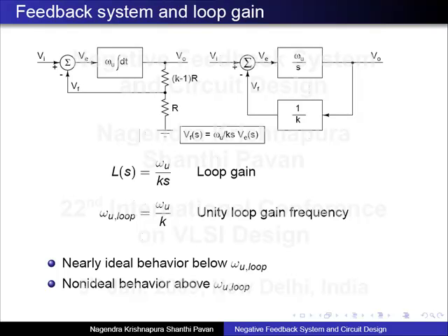What do you mean by non-partitionable? No. This doesn't really relate to any of the, I have not even discussed series feedback or any of the 4 categories, right? The bridge feedback or anything can probably be broken up into this. As a system, maybe you won't be able to identify the circuit in that way, but it can always be done like this. Any feedback system can be reduced to some form where you can identify the loop gain. Maybe it is very hard to measure and simulate and all that stuff, but it is there. The loop gain is there in the feedback system. So that is what we have done here.